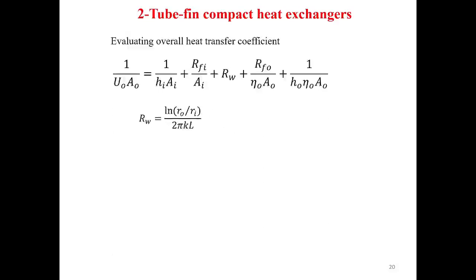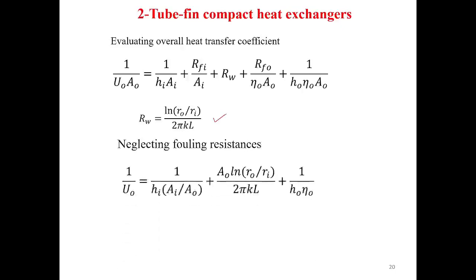Again, we talked about the overall heat transfer coefficient, as we said before. Here we indicated how to calculate the resistance in the wall. If you neglect the fouling, you'll get this equation. One thing that you have to remember is that in evaluating the overall heat transfer coefficient, for example, using this equation, we need to calculate, as we said before, the heat transfer coefficient using Kays and London figures, and also the overall surface efficiency.